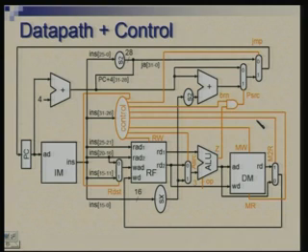Then we can also control this multiplexer by figuring out whether it is a jump instruction or not. So, now what is left is this opcode, the operation which ALU has to perform, and it will depend upon 6 bits which come from the function field.